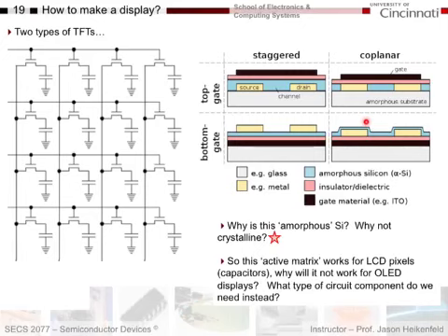In this case, the gate is buried underneath, and then here's your source and drain. Here's the semiconductor material, and I put a voltage here to get current through there. There's my insulator right there. And so you could look through these. I won't go through these in detail, but these are all thin films that are deposited and built up to create these four different types of transistors.